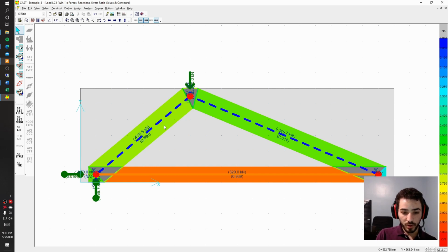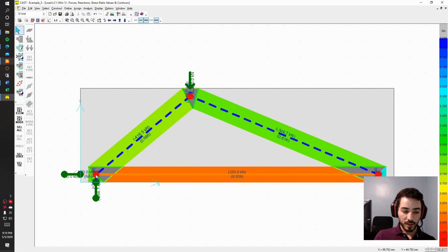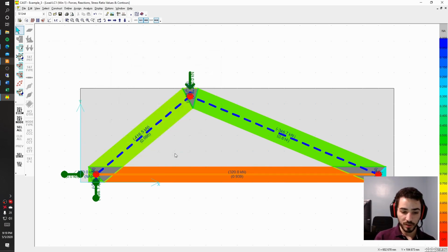and these results should be final for our model. If we wanted to, like I said, now that we know the area of reinforcement that we need, and since we have a good margin, it's most likely we won't need to update that. We can go back and calculate a more refined distance of this node based on the actual clear cover, based on the actual diameter of the bars.